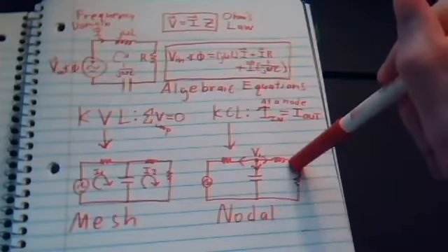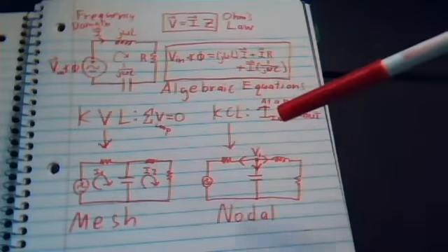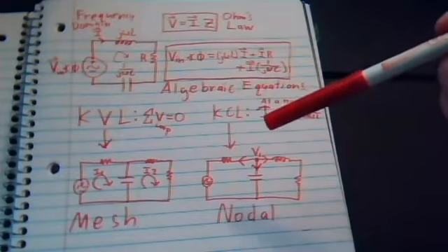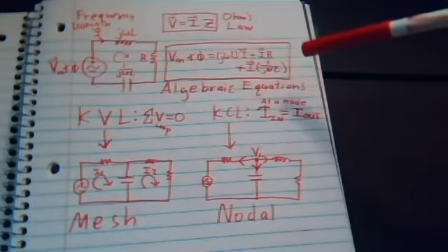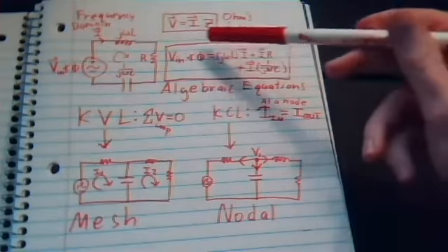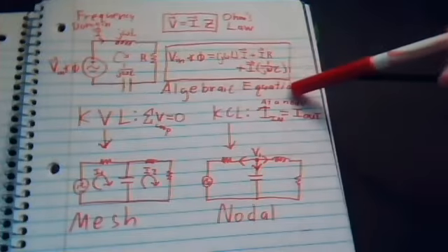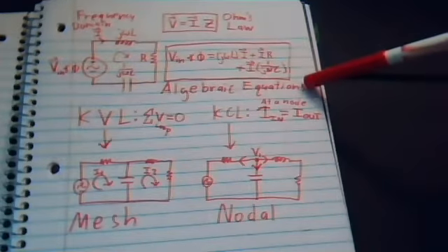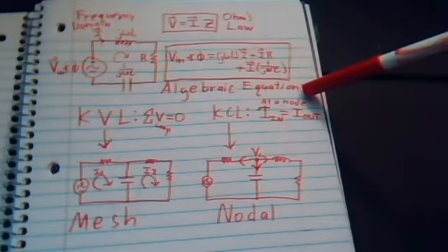We also have voltage division, current division. We can make Thevenin equivalencies much easier, superposition, all sorts of tools that we learned in Circuits 1 are now eligible for use in AC circuits. And perhaps the most beneficial part of this whole thing is that the expressions you get from performing these techniques will be algebraic in nature. You'll have algebraic expressions or equations that are not going to require differential equations.